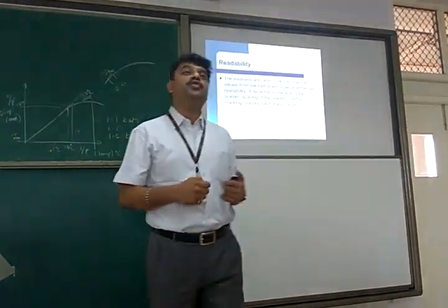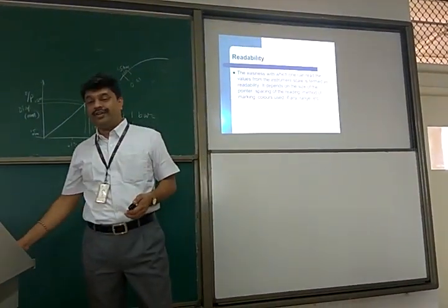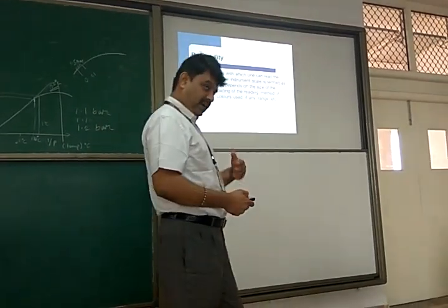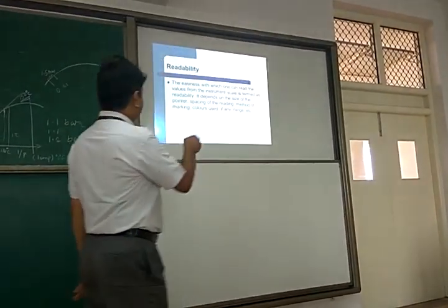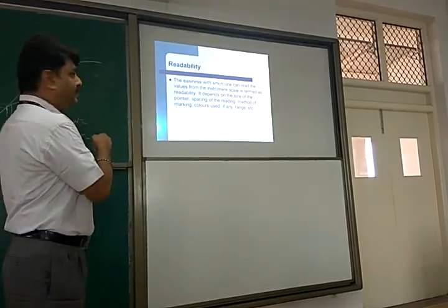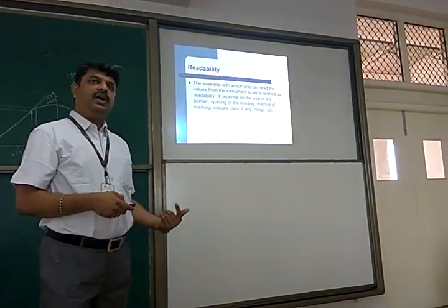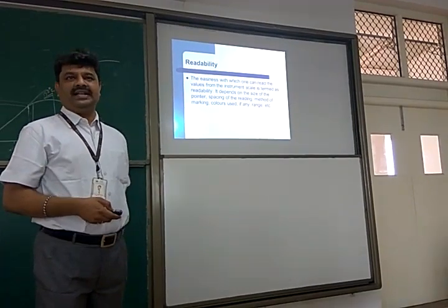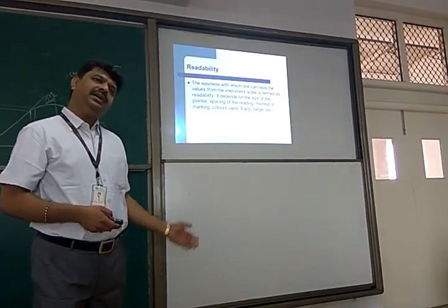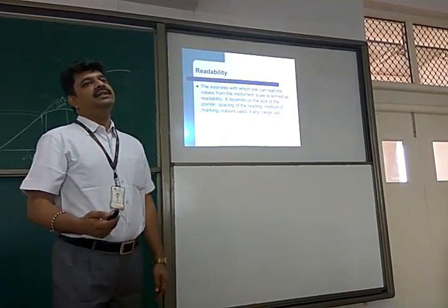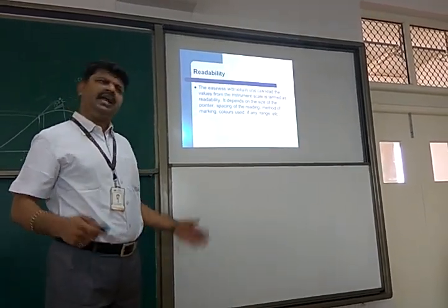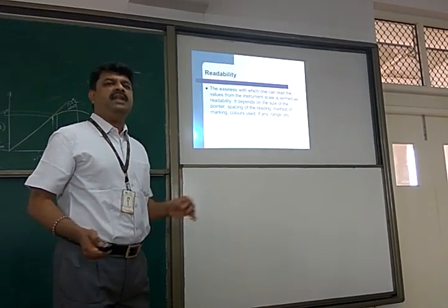So his eyes will be strained very much. In order to safeguard the operators, to qualify the gauge as an industrial gauge, that's the industrial regulation. That term is readability. If it is below 1.5, we say it is poor readability, not qualified for an industrial gauge. If it is 1.5 mm per division or above, then it is an industrial gauge. It can be any bigger than that. Minimum 1.5 mm.